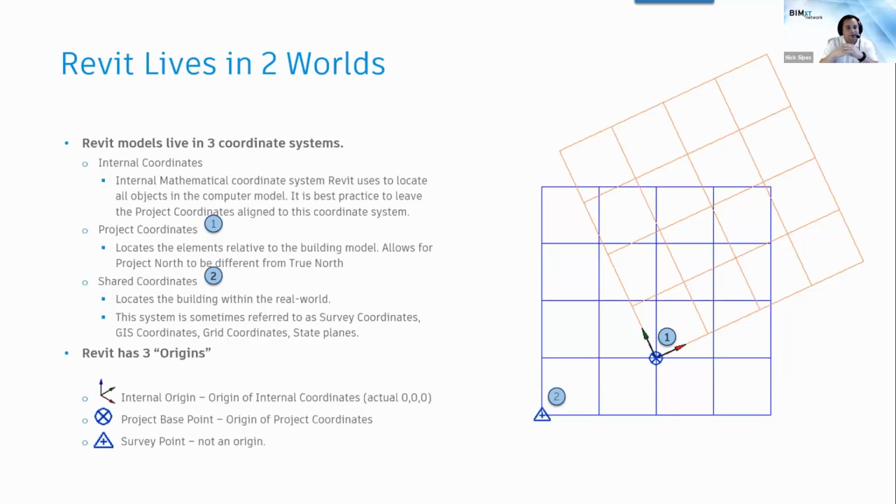What's nice about Revit is you can set up several shared coordinates in one Revit file. So if you have to, and I'm not saying this is a good workflow, but if you have to have one set of coordinates for, say, the contractor who did their point cloud in one coordinate system without looking at what coordinate system the drawings were in, you can set up the two coordinate systems, and because it's just a relationship, Revit just switches which one you're looking at.